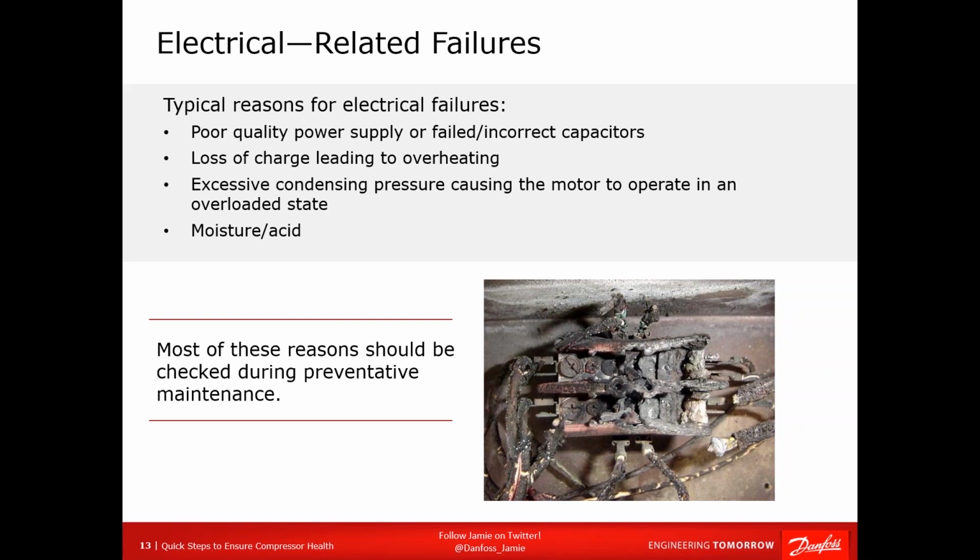If you decide to hook up a three-phase compressor backwards, that's never a good idea. Also, on the single-phase stuff, if you have a weak start capacitor, you're going to have a real issue because these compressors should start up with no hesitation. So if there's a delay in start, and I'll reiterate this later, you're drawing 6 times the amperage during that.